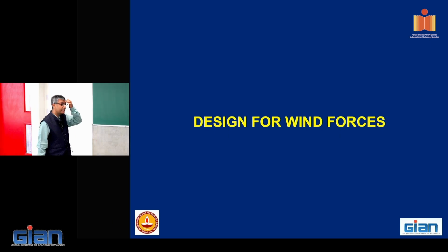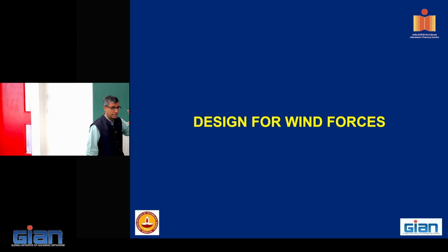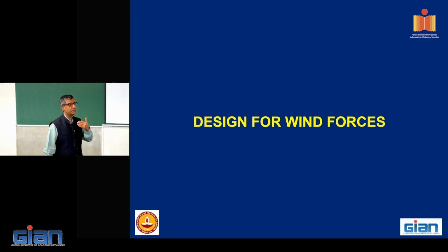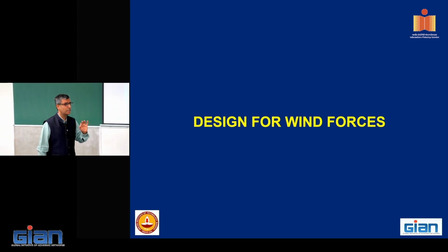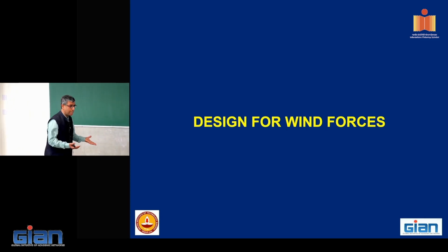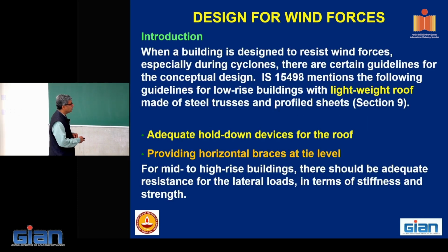Next, this is the analysis for wind. That means you're calculating the wind forces, then you may have a computational model where you apply the force and the model will give you the internal stress resultants, which are the bending moment, shear force, and axial force. Once you get those, then you are designing the building. Now, what are the issues of